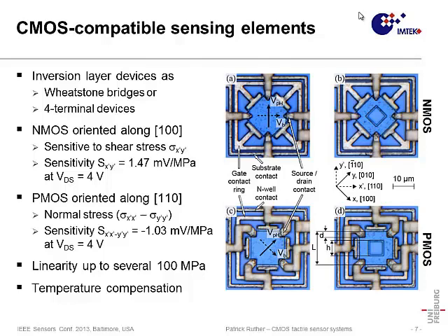These sensitivities clearly indicate that we can have a sub-megapascal resolution with these devices, and more important, looking at the linearity of these effects, we see that we can cover a broad range or a wide measurement range with these devices, from a few megapascal or less than a megapascal up to several hundred megapascal. Moreover, these effects are temperature compensated as long as we do not take into account the temperature dependence of piezoresistive effects.